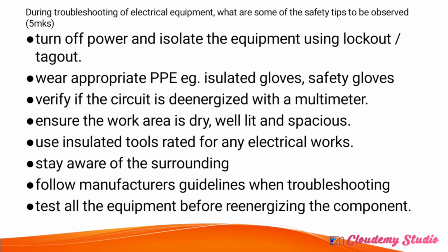You cannot find that the whole manufacturing process has been stopped simply because maintenance is being carried out. No. First, the maintenance team will have to turn off the power and isolate the place they are working on. If it's the manufacturing or processing department, all other departments will still carry on with their activities as they do maintenance on the department that is faulty.